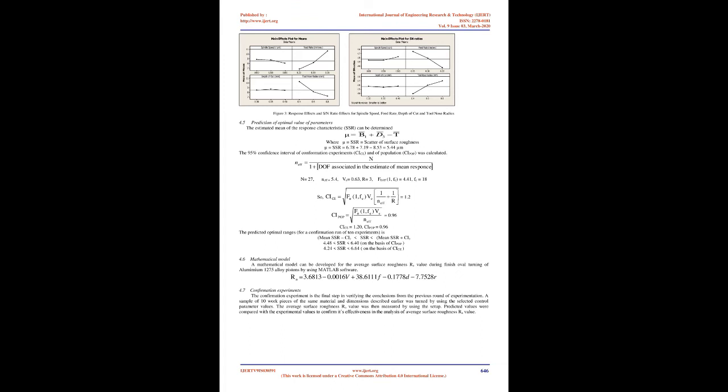The influences of feed rate, P equals 52.75%, and tool nose radius, P equals 34.71%, are the most significant. The influences of spindle speed, P equals 1.82%, and depth of cut, P equals 0.68%, are less significant influencing factors.